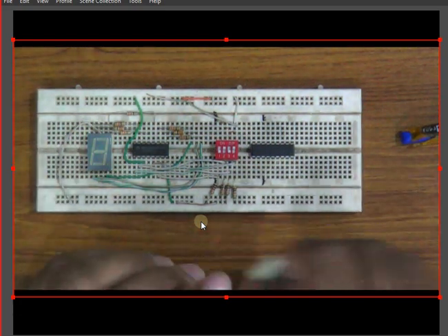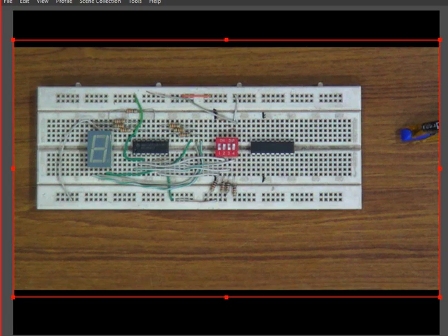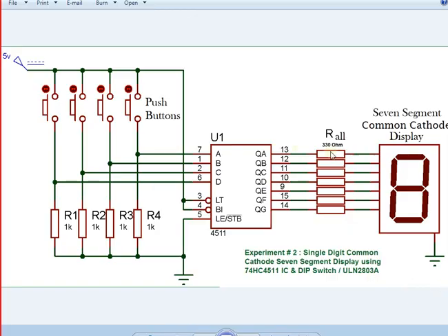The only thing different is that this time it's not common anode, it's common cathode. Common cathode means that instead of providing from that common central point, this is grounded, which means you are going to provide a sinking path over there. And I hope you remember I told you that sinking meant the current was going to sink towards the ground.